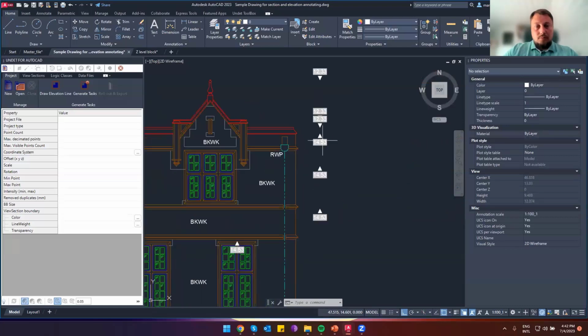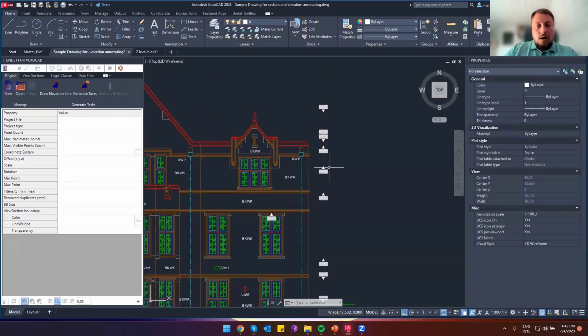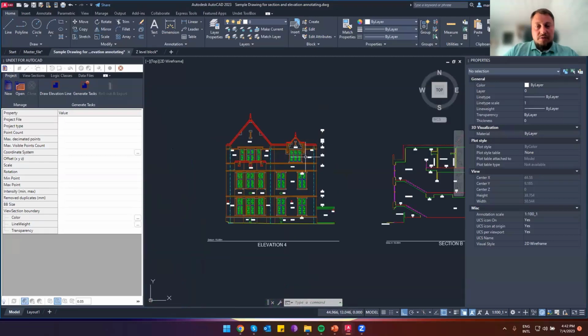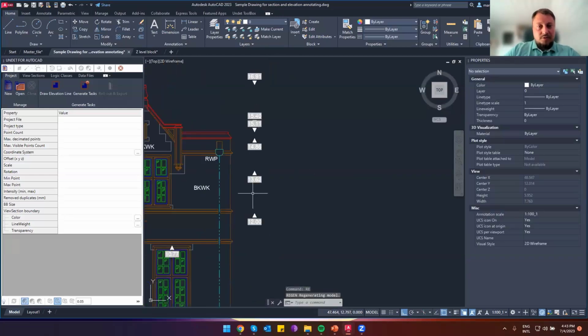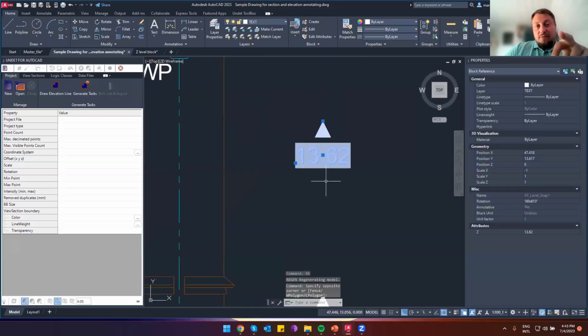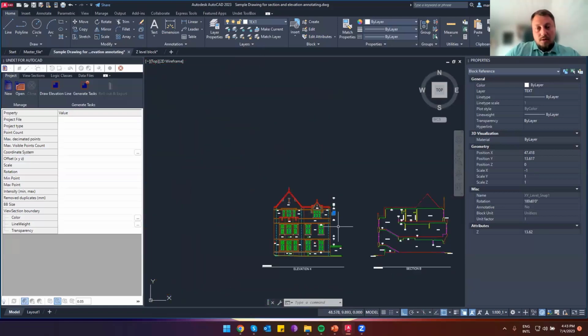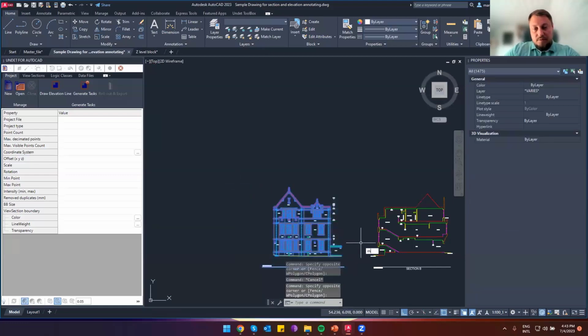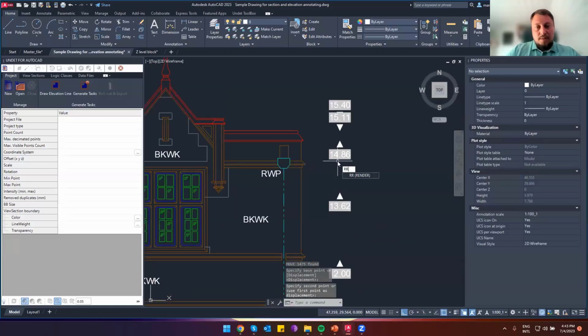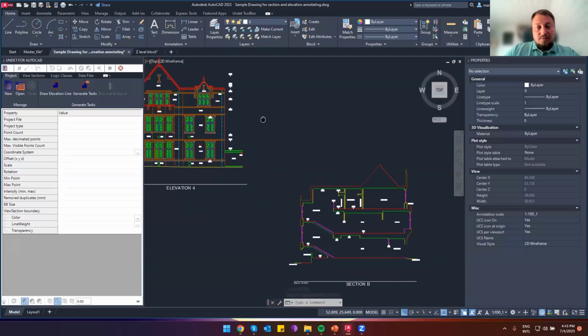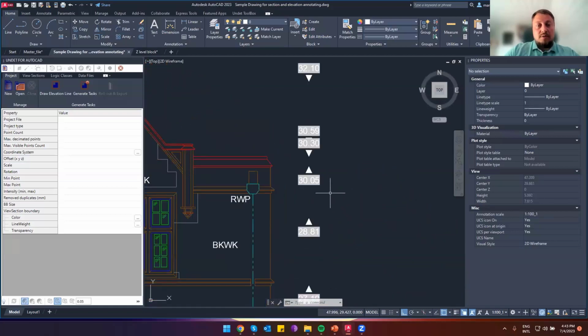And always when you're delivering the drawings to your customers, it's better not to send the blocks, because if a customer will try to move these blocks, I forgot to regen. Now it's showing the correct values, because if you send these blocks to the end customers without exploding them, the customer can very simply move our section or facade drawing to another level, type regen, and all values will be automatically changed. So we recommend to explode these blocks, but the procedure is the same.